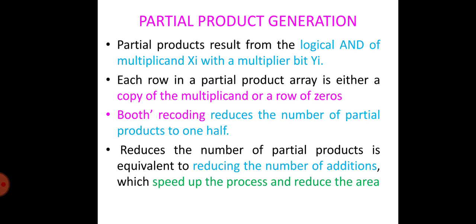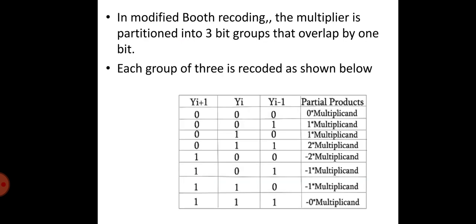In case of a multiplier consisting of all ones, all the partial products exist, while in the case of all zeros there is none. This observation allows us to reduce the number of the generated partial products by half. Assume, for example, an 8-bit multiplier of the form 0 1 1 1 1 1 1 0, which produces 6 non-zero partial product rows.